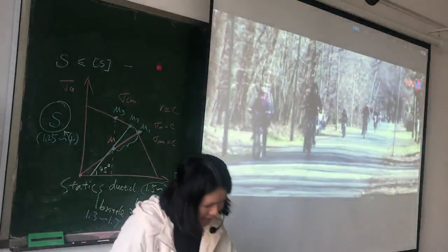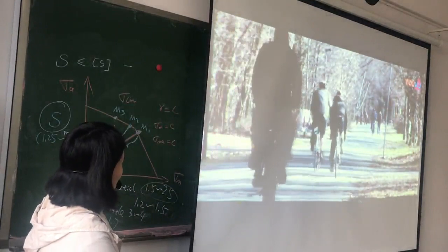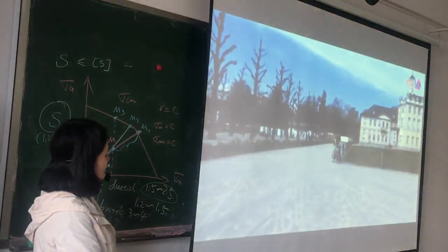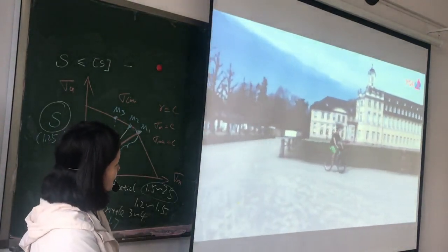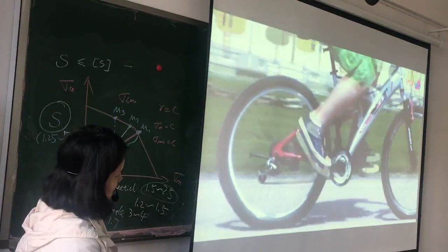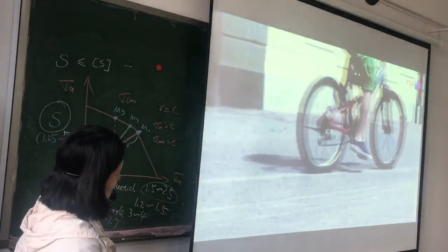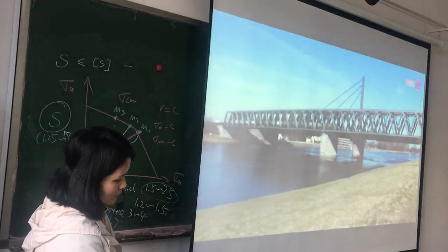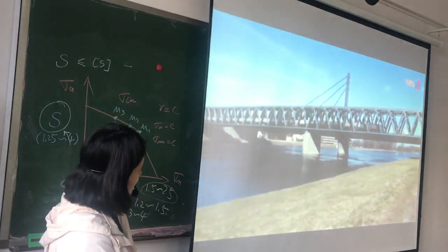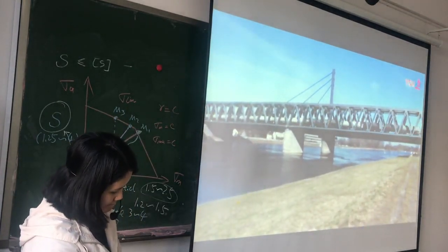Components are exposed to periodically varying loads without us being aware of it. The crank arms are alternately under load, then swing back almost load-free, are under load again with the rhythm of pedaling. The spokes, the pedals, even the individual links in the chain are stressed periodically. Also, the railway bridge over the River Rhine, seemingly totally static, alternately has to bear the additional burden of a heavy freight train and then only its own mass.